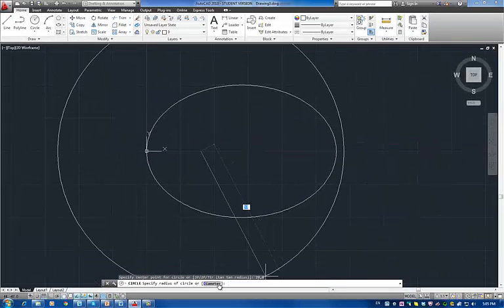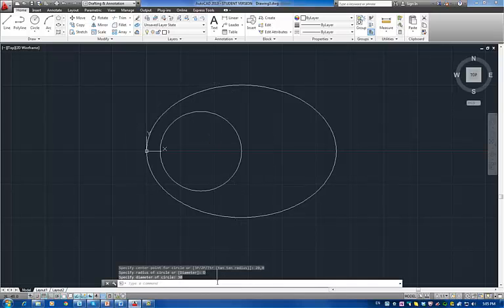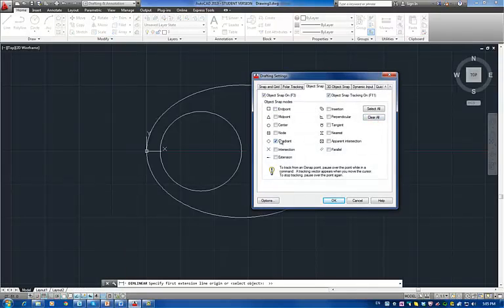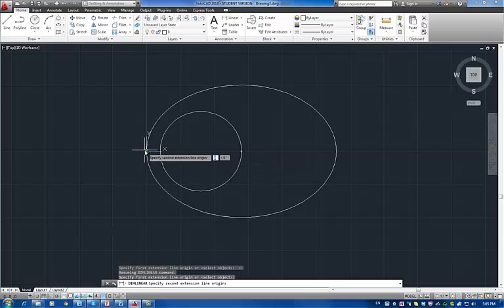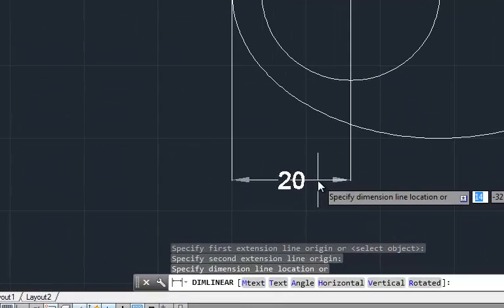And then I want to change this to diameter, because that's one of my circles. Diameter is 30. And then I can use the center point option. I can check if location is good by going here, settings, and I can check the quadrant in the center and see what is here in between the quadrant and the center. It's 20. So from now on I can use that center for the location.